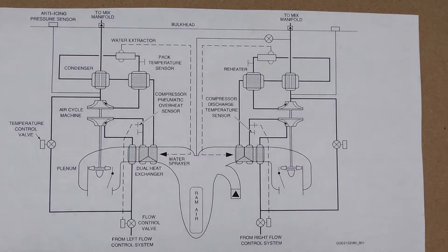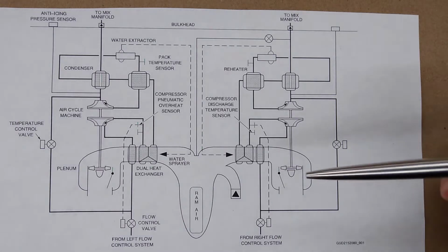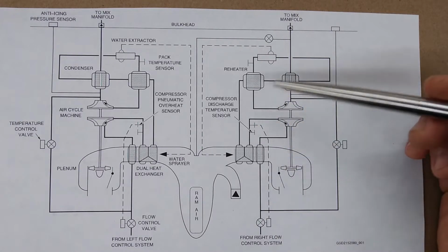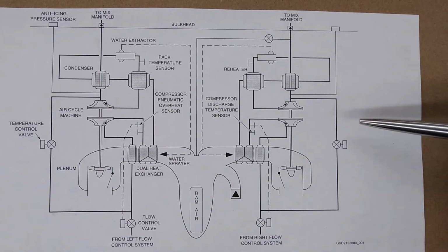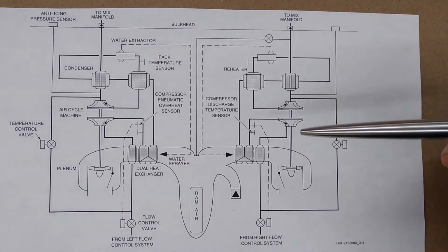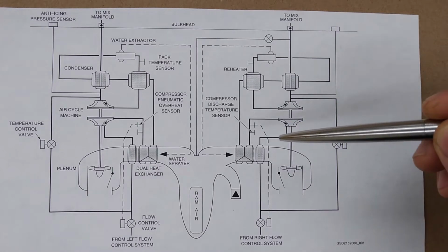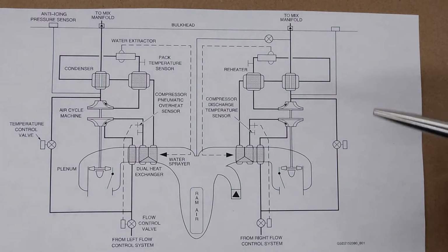The air cycle machine, this whole air conditioning system, is an open loop. The previous system that we looked at in part 1 was a closed loop system because it recycles the refrigerant over and over, using the same refrigerant to carry heat from one side to the other, from inside to outside, or whichever direction you want. In an open loop system like the air cycle machine, you don't have that. Air is your cooling medium, is your refrigerant, and is also the fluid that you're pumping into the cabin.